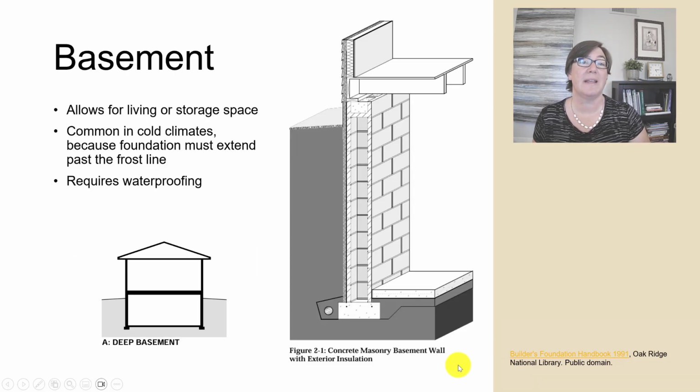Let's look more closely at that basement foundation type. Basements are popular because they add living space or storage space to your home. And they're more common in cold climates than here in the San Francisco Bay Area because in cold climates you need to extend your foundation past the frost line, right, which is the area of the soil which will freeze during the winter. And if you're going to do all that work anyway and make those deep foundations, you might as well add the usable space.